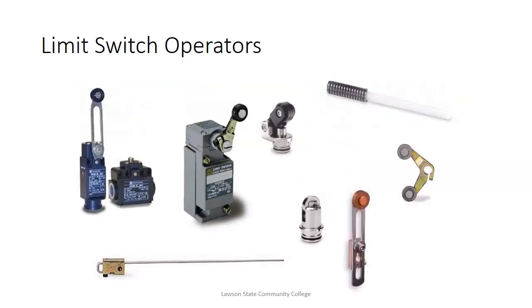So these are limit switches. This is pretty obvious how they work. What they've got is an operator. The operator makes physical contact. It causes contacts to change positions, and it gives us a signal that we use to know when it's in. So the position of these would be critical. I don't know how many on the Amatro line. I know we have at least 2 on the Festo line. I think we got like 3 or 4 on the Amatro line, which is the one that we don't have these big ones.